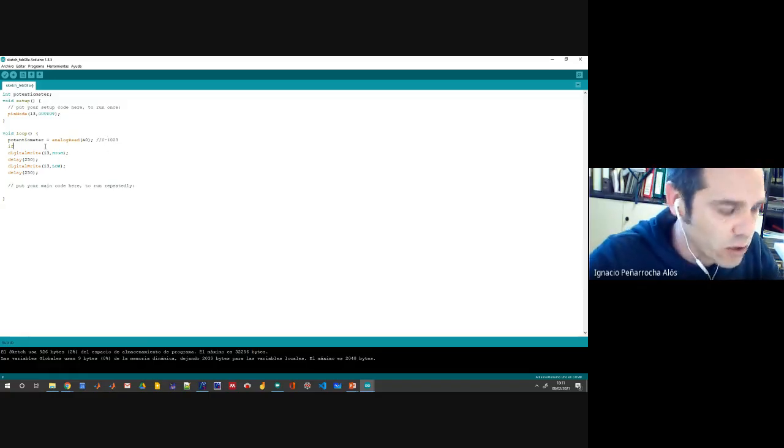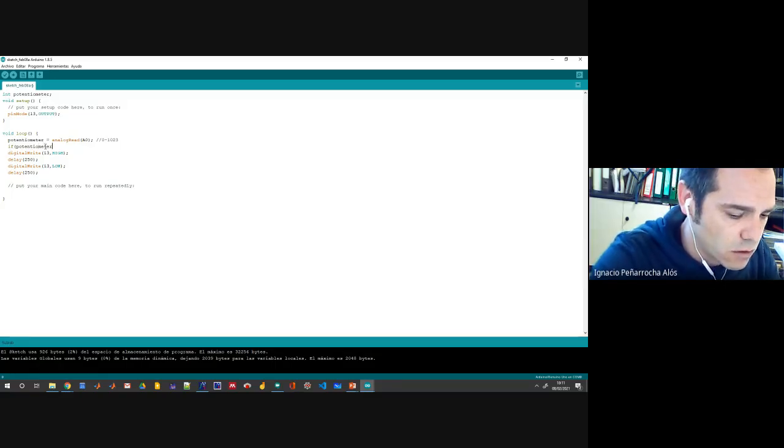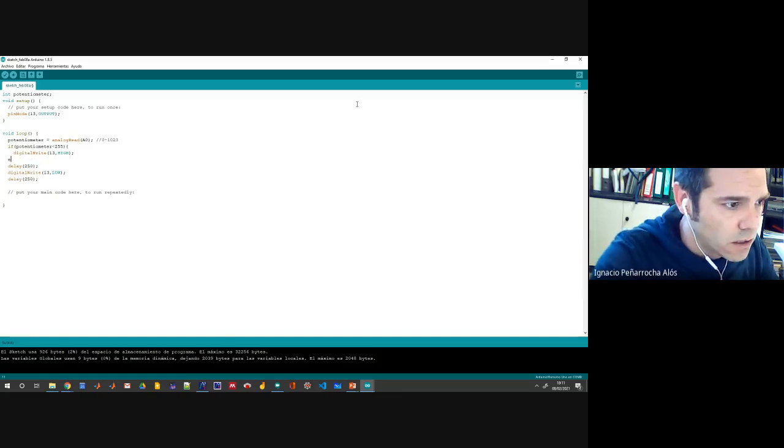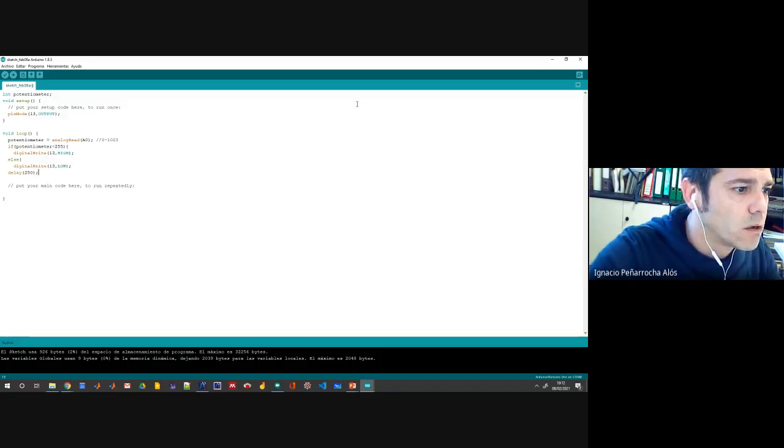So I say, for example, if potentiometer lower than 255, then digitalWrite high, else digitalWrite low.